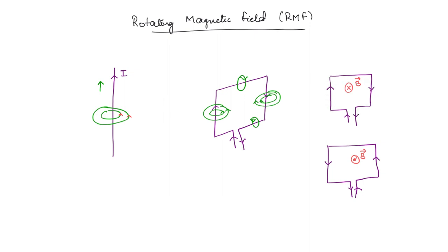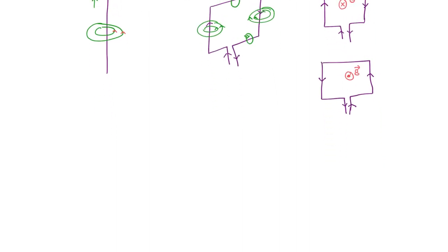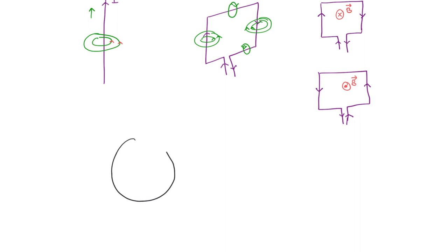So these are some of the basic concepts. Now you take a machine, the stator of a machine, and for this stator, let us take slots here, so that we can place the conductors, the coils. The coils we will mark with red. So this is one coil and this is the other side of the same coil. We are seeing from this end, the top view. If the current is flowing in one conductor in the upward direction, let us take it to be outward, then on the other side the current will be going into the plane.